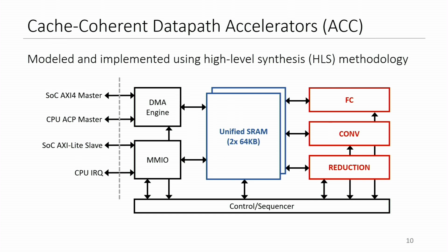Okay, so this is a simplified block diagram of the accelerators we attached via ACP. It's based around a unified SRAM buffer with dedicated data paths for fully connected, convolution and reduction operations. And this design actually was modeled and implemented using high-level synthesis.